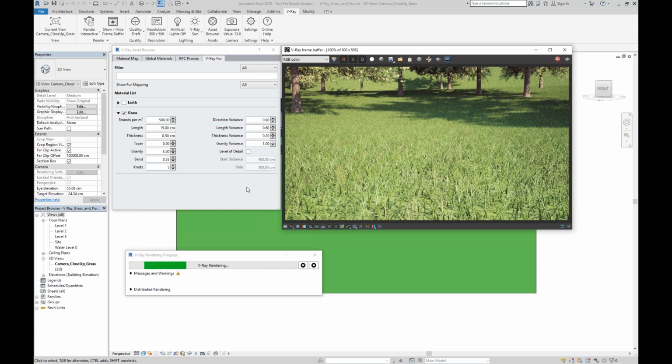Well, Vismat is a slightly outdated file format. You can open it with the V-Ray standalone material editor and you can resave it so that it will turn into a VRMAT, but I cannot guarantee that it will render correctly. So converting is the way to go? Yeah, basically. Some Vismats would work, but other ones would produce strange results.